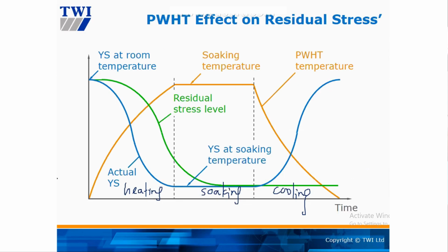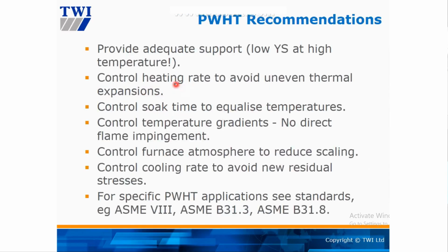So please memorize a bit: what happened during heating, during soaking, and during cooling for elastic strain and residual stress. All right, the PWHT recommendation here is to provide adequate support, control heating rate over uneven expansion, control soaking temperature, control furnace, control cooling rate.